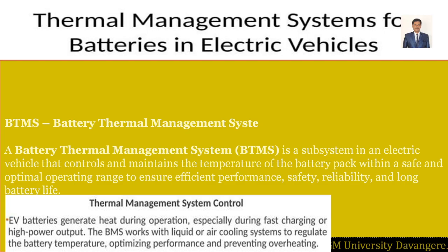If the temperature is going to be around 65 degrees centigrade, what actions are you going to take? Suddenly they should have the power cut, and it stays cut till the temperature reaches back to the normal 40 degrees centigrade. That will prevent safety issues for your batteries. So that is what you have to think about for hot problems when the temperature rises to the maximum values.